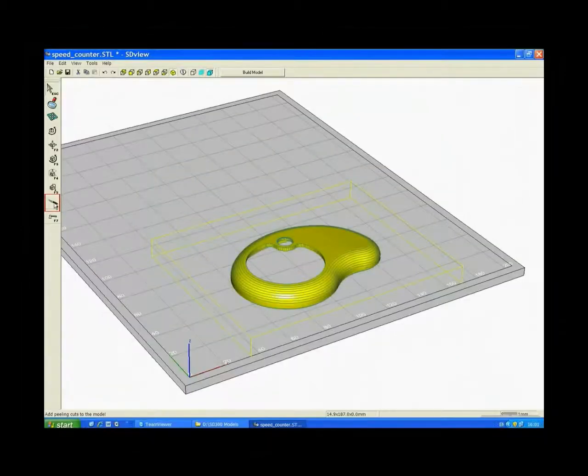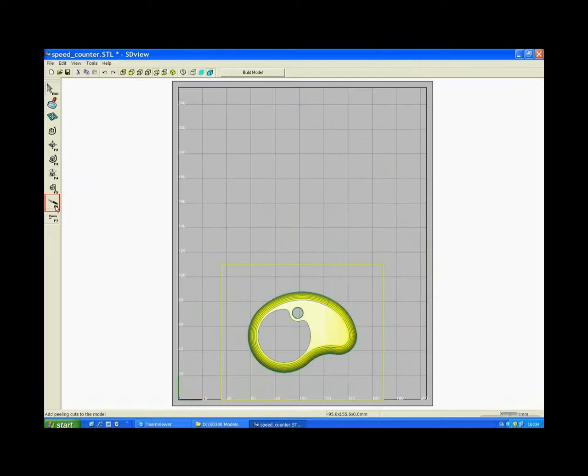When selecting the Peeling Cuts feature, a cross will appear in the graphics area of the part. In order to place a peeling cut, left-click at any position required. In this case, I will select the top view and place a peeling cut in the center of the part. When I reach the bounding box, I will have a snap marked as a purple-colored square.